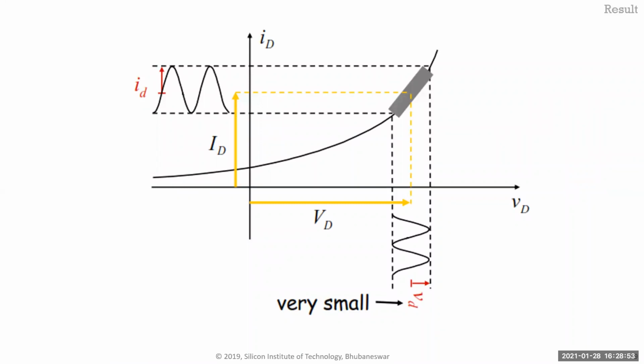This is kind of showing you in a pictorial view. So basically you're taking a small linear portion. Obviously this also has some nonlinearity in it. But like I said, if the nonlinearity is small enough that, let's say in this case of audio, you cannot hear it, then it is fine, right? So for example, I cannot hear anything below minus 70 dBc or 80 dBc, or at least I can. So you keep going till it is minus 80 dBc, then I'm good, right? Before it was maybe minus 10 dBc. So in other words, however much signal I was giving, the distorted signal was just 10 dB lower than that, which is very, very high, right?